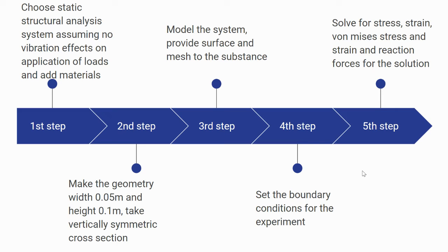In the third step, we model the system, provide surface and mesh to the substance. Then we set the boundary conditions for the experiment. Then we solve for stress, strain, von Mises stress and strain, and reaction forces for the solution.